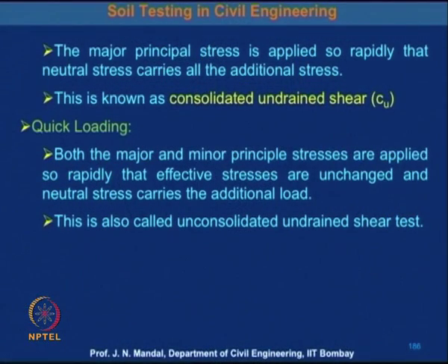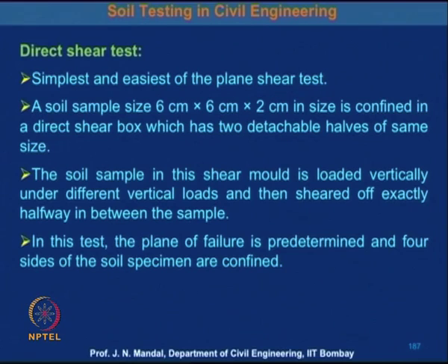And in quick loading, both the major and the minor principal stresses are applied so rapidly that effective stresses are unchanged and the neutral stress carries the additional load. This is also called the unconsolidated undrained shear test.